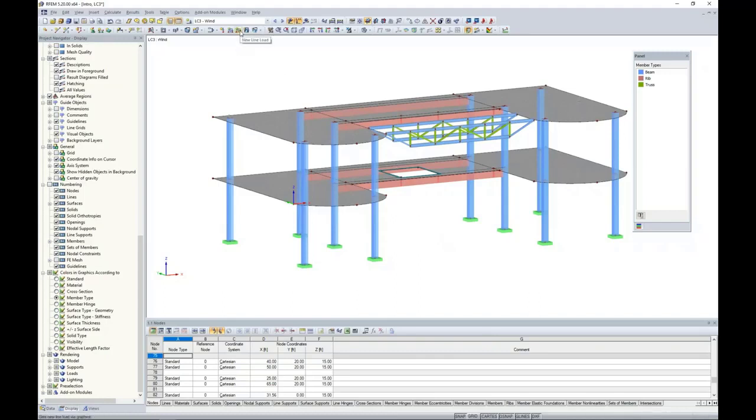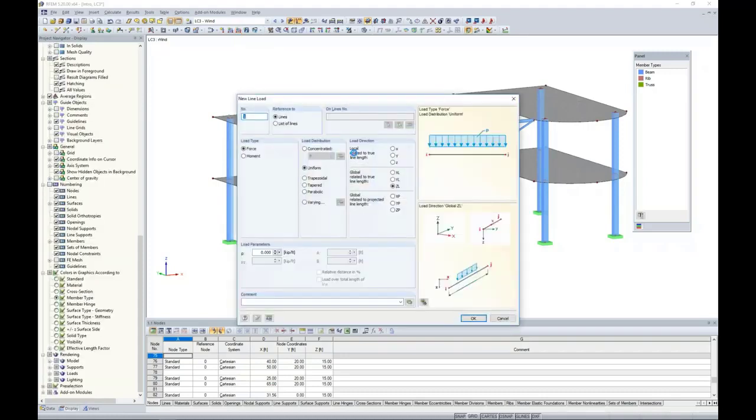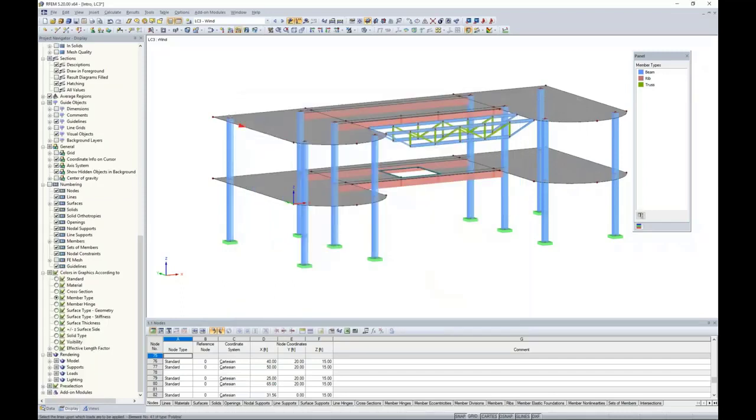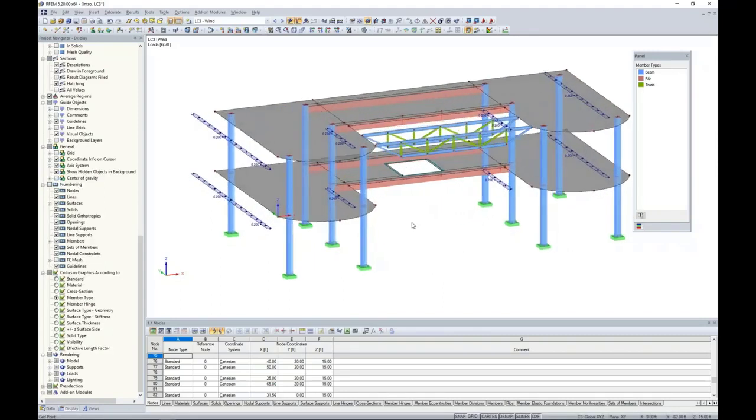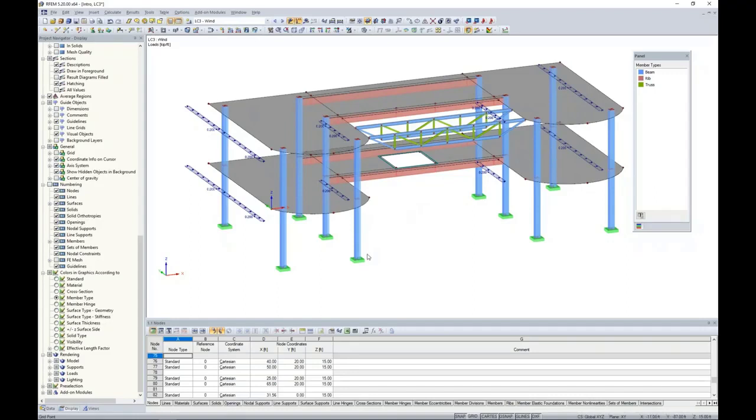For today, I want to just apply a very simple line load to these diaphragms. So we will select a new line load up in my toolbar, and the direction will actually be the global X projected direction. The magnitude here will be 0.2 kip per feet. So what this allows me to do now is to click on these concrete surfaces and to apply this lateral load at those exterior line edges. So again, a very simple application for today. In reality, we'd want to apply different loading scenarios for wind to our structures.